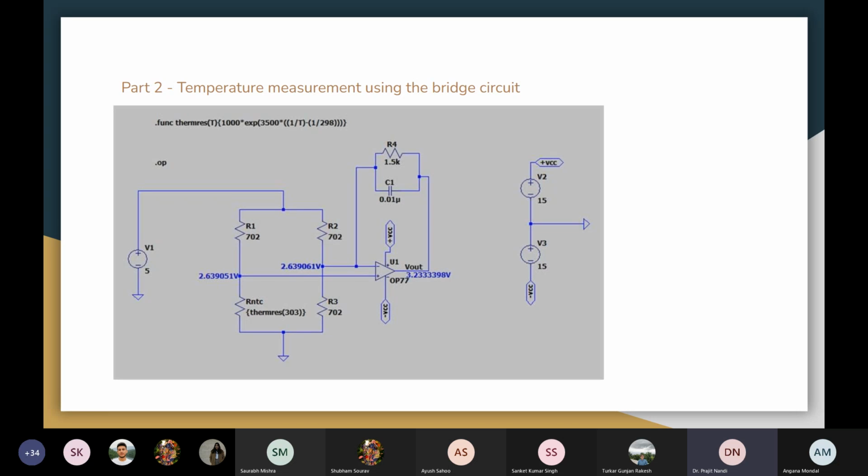So basically the capacitor has been placed for stability reasons. And if you were to do a Bode plot, you will find the answer pretty easily. It is not because of noise that it has been placed. Typically for noise, we do not place discrete components as such. I'm talking of device noise, not a large signal power supply noise or IO switching noise.